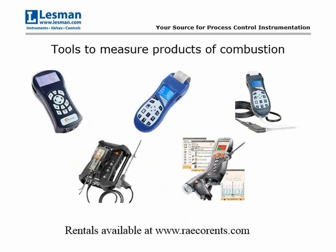Another tool that you would want to use, especially with this emissions-driven application, would be a combustion analyzer, something that would go through and would tell us what the NOx and the CO levels are coming out of the process. It also gives you an O2 reference so that you can correct for oxygen levels.